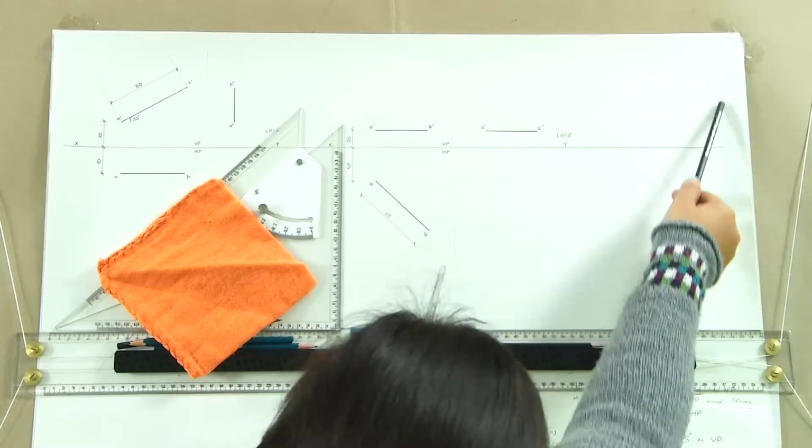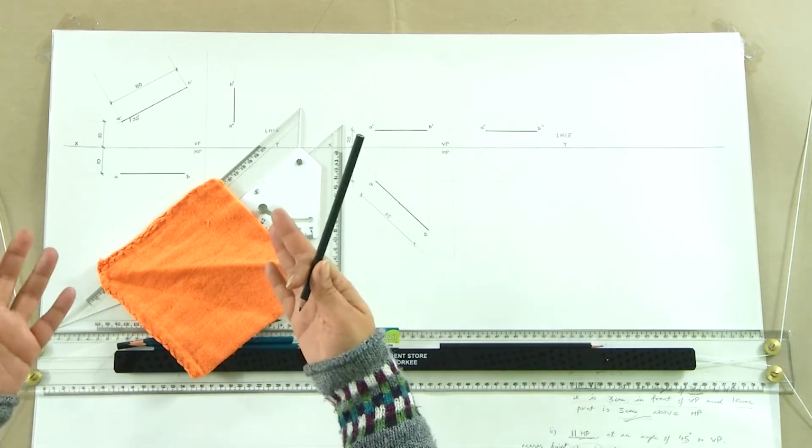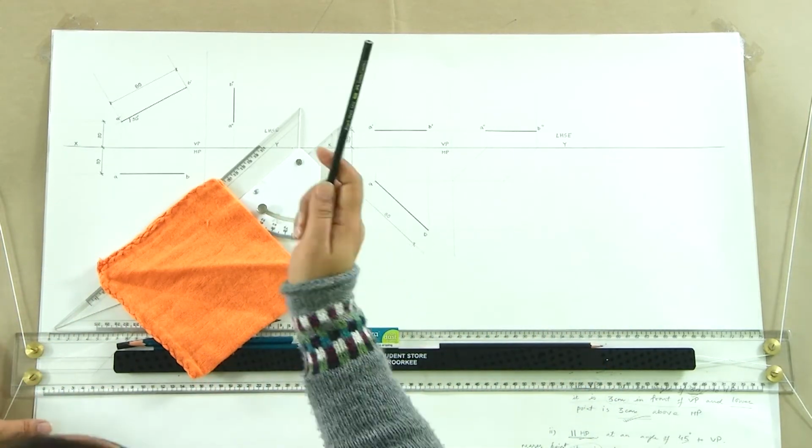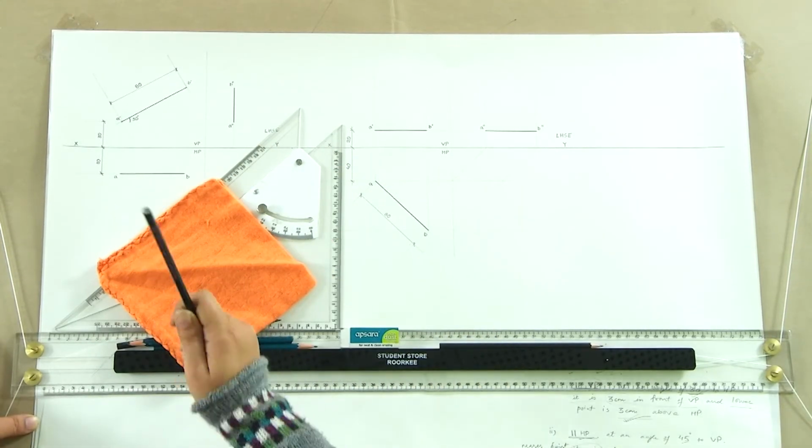And the last thing that should be darkened on your sheet is the border. I am not making the borders here, but if you are to make the complete sheet for say submission in your class, you need to make a border, write everything, which should be the last thing that you do. Darkening of the border: light border you could do, dark borders you should do later.